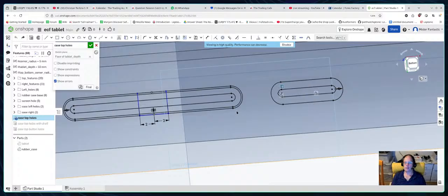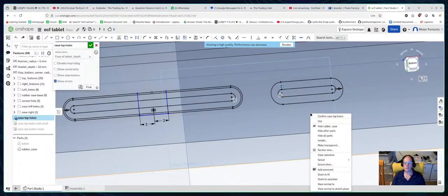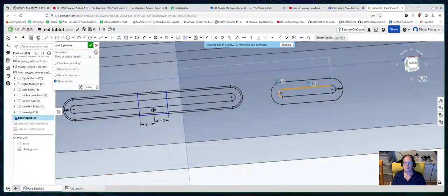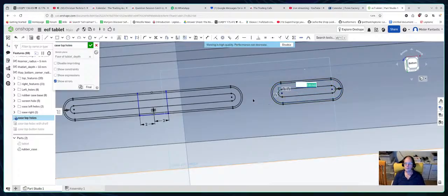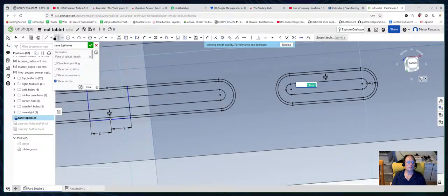So this one's an actual power button. So what we'll do is we'll select all of this and do an outline again of 0.8 mil. So we can, 0.8, not that way, the other way. Save. So that's the actual power button, but we need it to be able to actually connect it somewhere, so we'll put a corner rect in here so the ends will be connected.